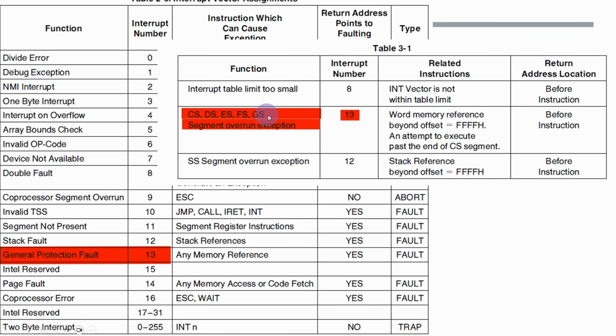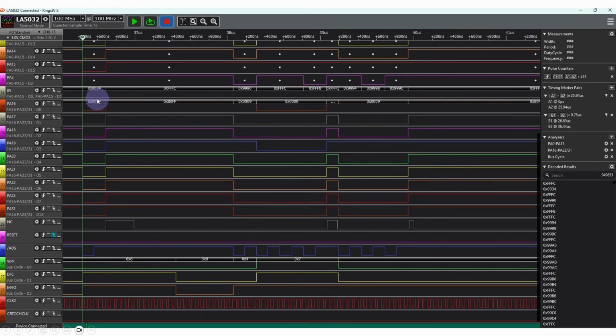which will be 9090, and it'll also read the program counter address off of the data bus, which again will be 9090. So because we're setting the data bus always to be 9090, the address that this is going to pick up to run this particular interrupt is going to be 90909090.